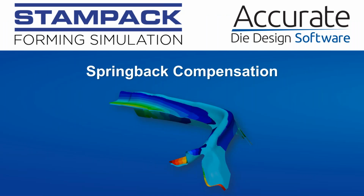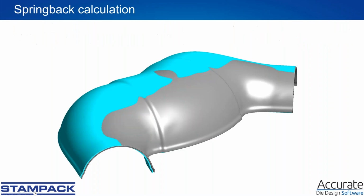Let's speak once more about springback compensation. I have another example for you. This is a typical part where springback is difficult. You see here the sheet after springback, and this is the sheet before springback. The part is maybe 600 millimeters long, I think. And we have here in this area, I think, 3 millimeters deviation to the nominal.